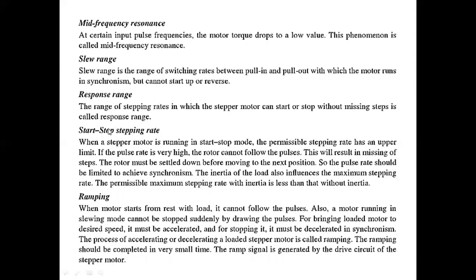And next one, response range: a range of stepping rates in which the stepper motor can start or stop without missing steps is called response range. The synchronism definition also comes towards the response range, same meaning. Why? Because first two switches are turned on and the A coil is excited. Next B coil is excited. Next two switches are to be turned on, without missing the steps to rotate the rotor.